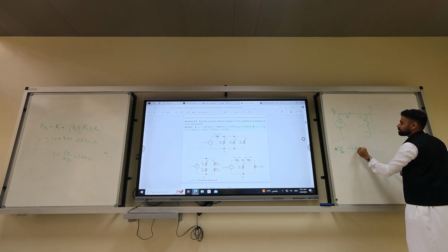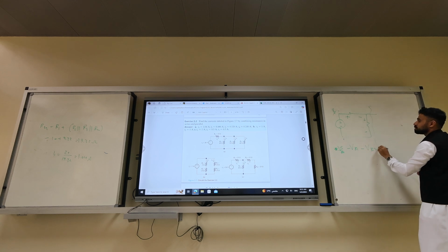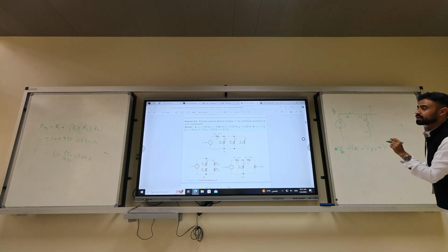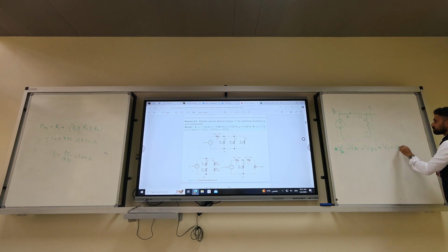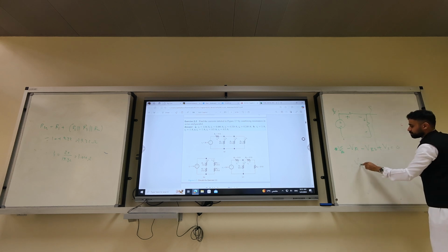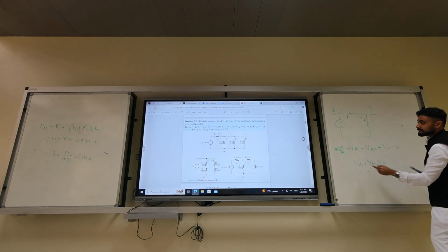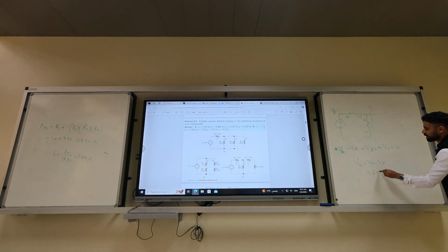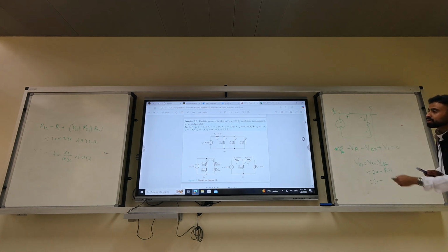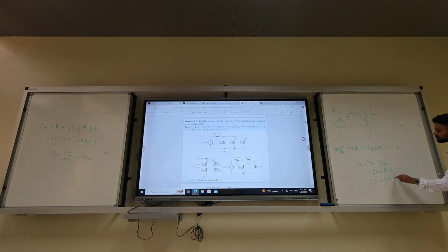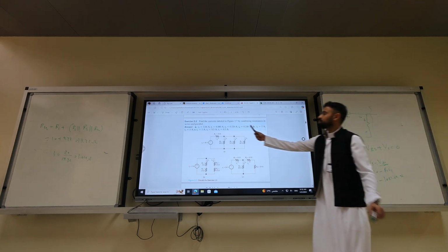Minus VR1 minus VR2 plus VS equals 0. So what is VR2? VS minus VR1. What is VS? 20. 20 minus VR1. What is VR1? R1 times I1. It's going to be 20 minus 10 times 1.04. Calculate the answer. You will get 0.32.